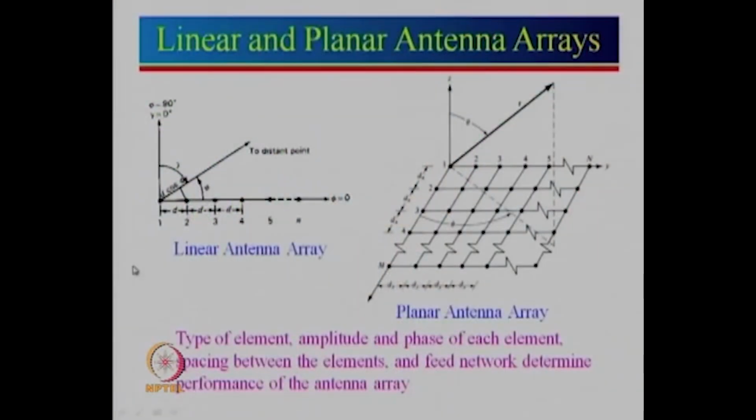However, if I use a directional FM radio, I can get a much better signal. However, the majority of the time we don't use a directional FM radio. There also we still use an omnidirectional one. But if we use a directional antenna, one can get a much better quality, because you know where the FM transmitter is. However, if we need a very high gain, then we can use arrays of these antennas.